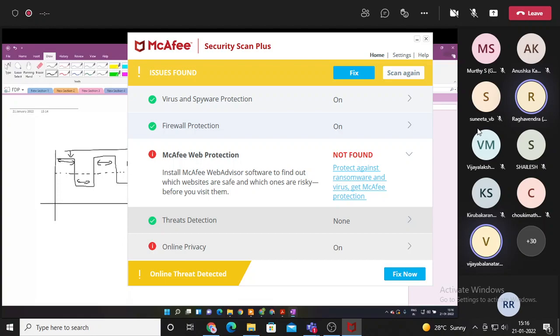So the very first step in visual light communication is not matched filtering. We don't need to do matched filtering over here since it's not a radio wave. We do a DC removal in order to ensure that the DC offset is gone. Actually, we don't consider it 0, 1 yet. I'm sorry. This is the threshold. We subtract this waveform with a DC value. So let's say 3 is the amplitude value that it's offset by. We subtract the entire signal by 3, and finally we get a proper waveform that looks like this.